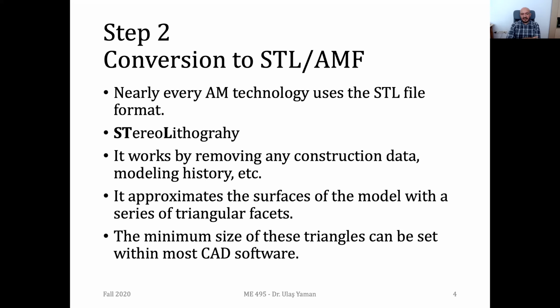So in summary, once you decrease the size of the triangle, the size of your file will be increased, but the resolution will be better. And if you increase the size of the triangles, the number of triangles will always be decreased, and the size of your STL file will be smaller.